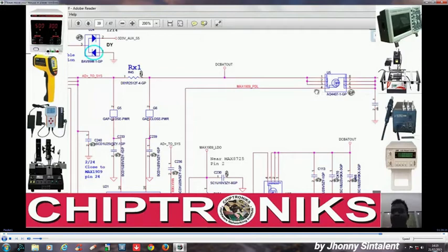If you check with a multimeter, when adapter is present over here, then the value at this gate would be high, and in that case VGS would be 0. So this MOSFET will turn off, no current will go across this. Similarly, when you have removed the adapter and battery is present over here, this gate value would be low and it will drive current over here.